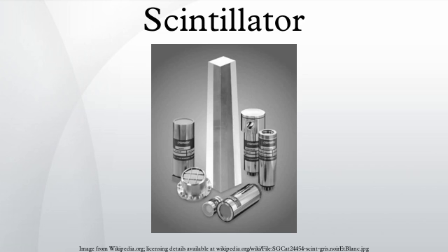Resistance and good behavior under high temperature, high vibration environments is especially important for applications such as oil exploration. For most scintillators, light output depends on the temperature. This dependence can largely be ignored for room temperature applications since it is usually weak. The dependence on the temperature is also weaker for organic scintillators than it is for inorganic crystals, such as NaI(Tl) or BGO. The coupled PMTs also exhibit temperature sensitivity, and can be damaged if subjected to mechanical shock. Hence, high-temperature rugged PMTs should be used for high-temperature, high-vibration applications.